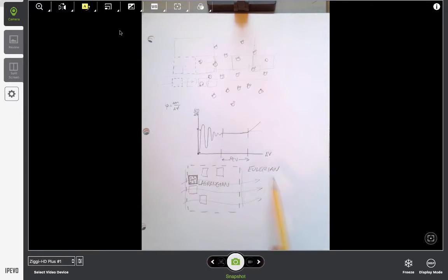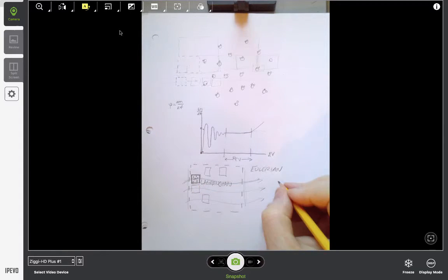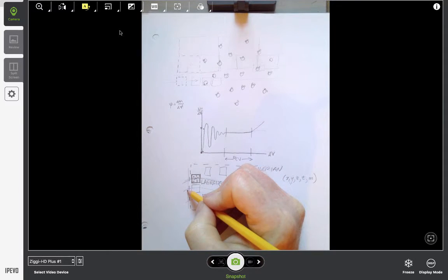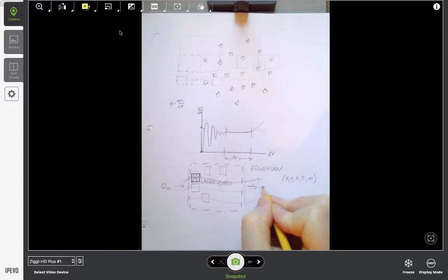They're not equal to one another, but they both can be used to describe fluid behavior, and each one has advantages under certain situations. The parcel method is especially useful when we're interested in a particular identity of fluids. So, Lagrangian coordinate system, the path the particle is going to take is important. The parcel will have attributes like position, x, y, z, t, and have a mass. In the Eulerian system, we have attributes like flow, discharge in, discharge out. Two different ways of looking at the same behavior.